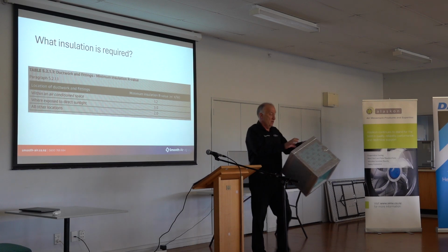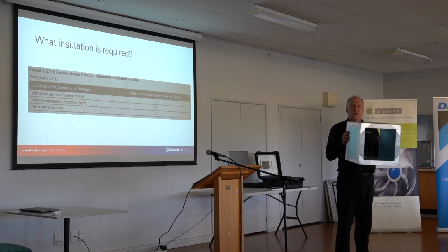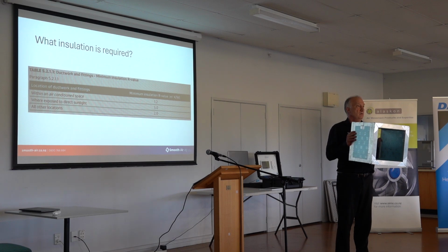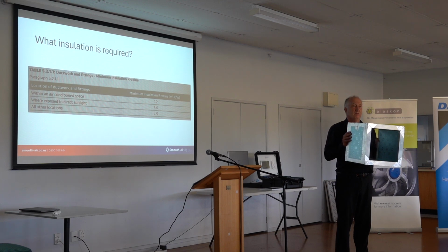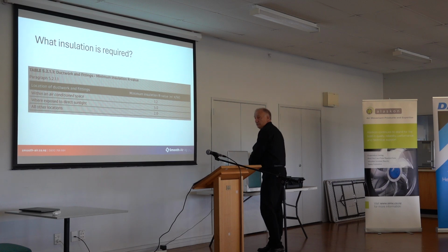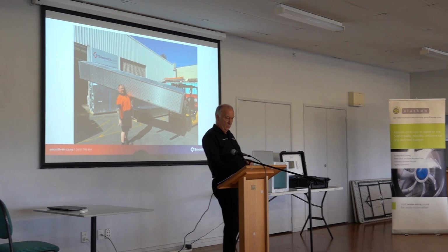Anyway, 3 thicknesses. It's about half the gauge of wrap duct. So this is 42 mil thick, whereas if you get galv duct and you wrap it, it's about 75. Bit of a no-brainer. I know what you're thinking, wow, this guy's onto it.